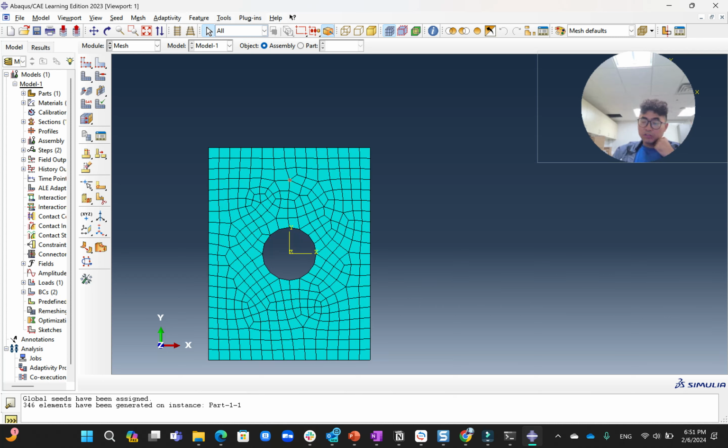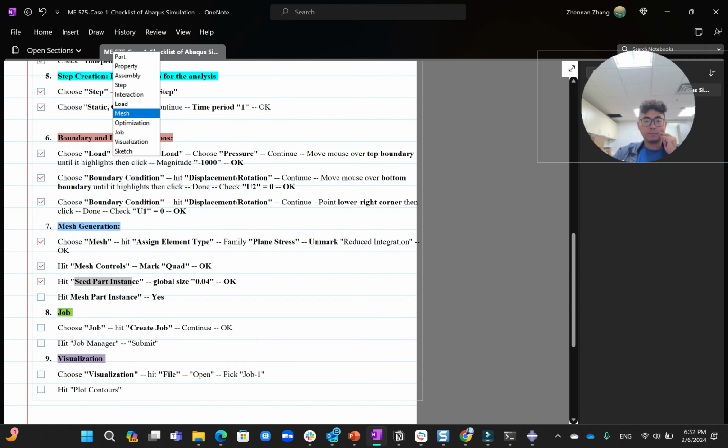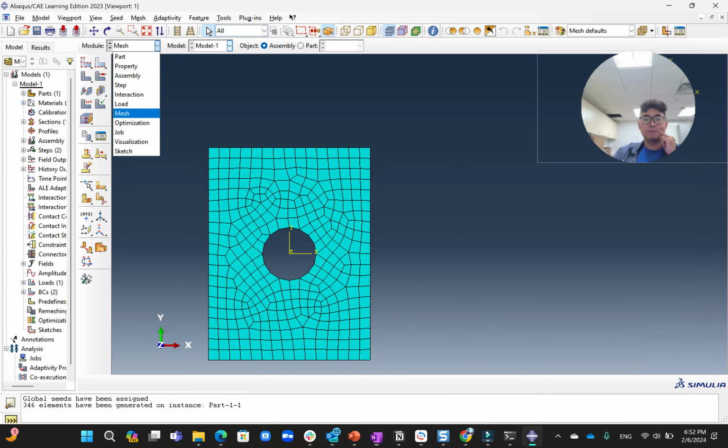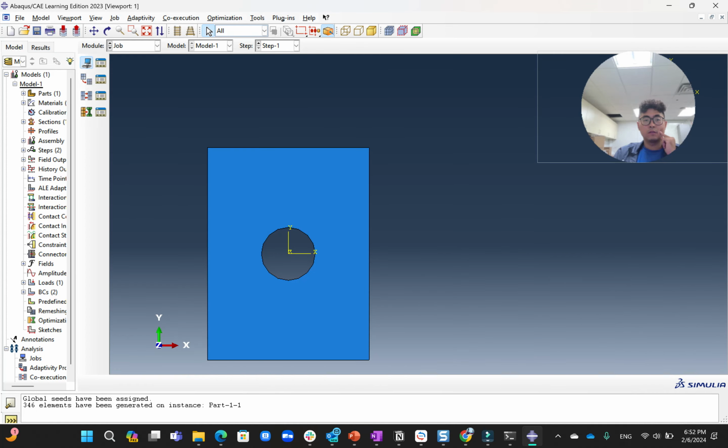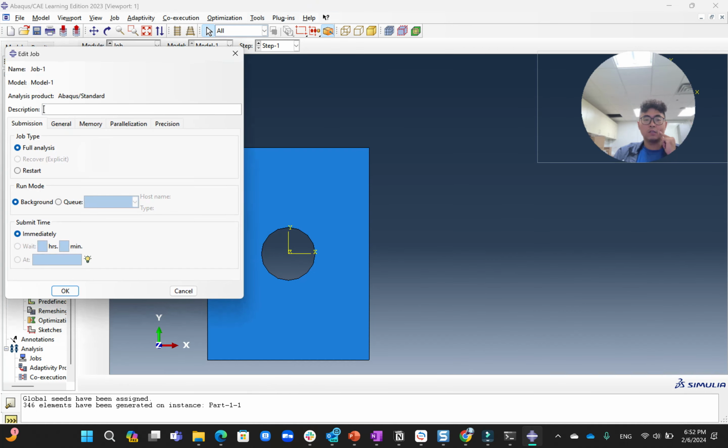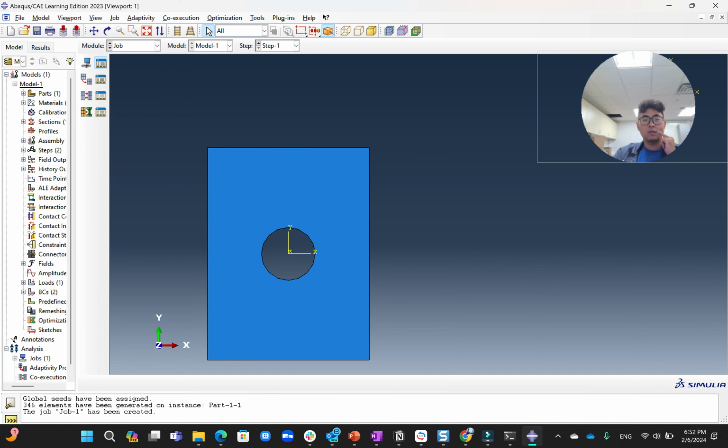Now you have almost finished every step in this simulation. The next one, run your simulation. In the job module, choose create job, and submit your job. Create job and continue. Okay.